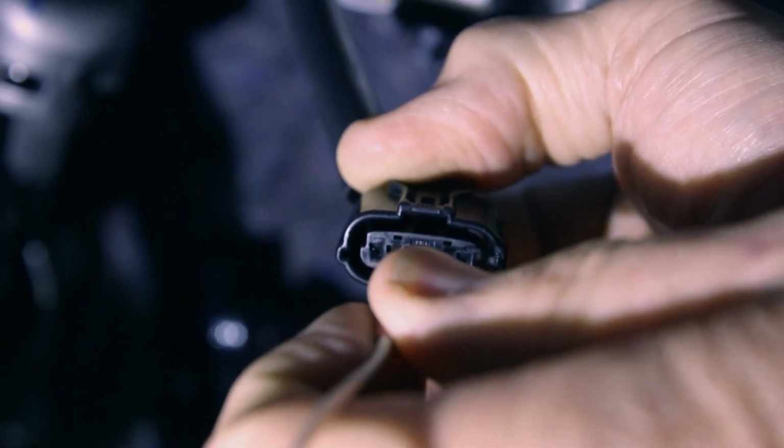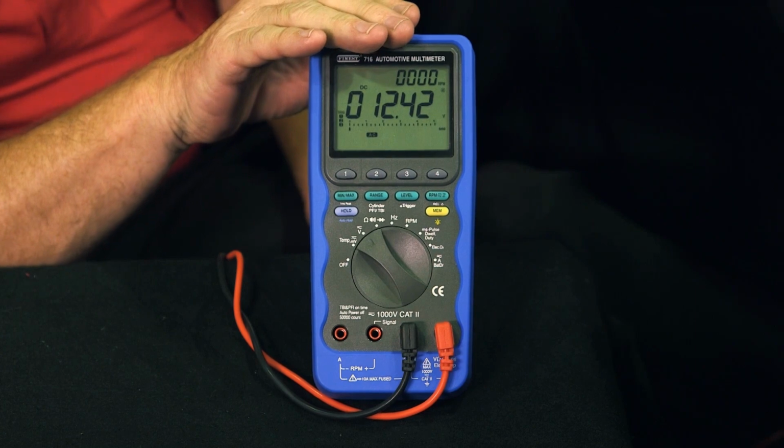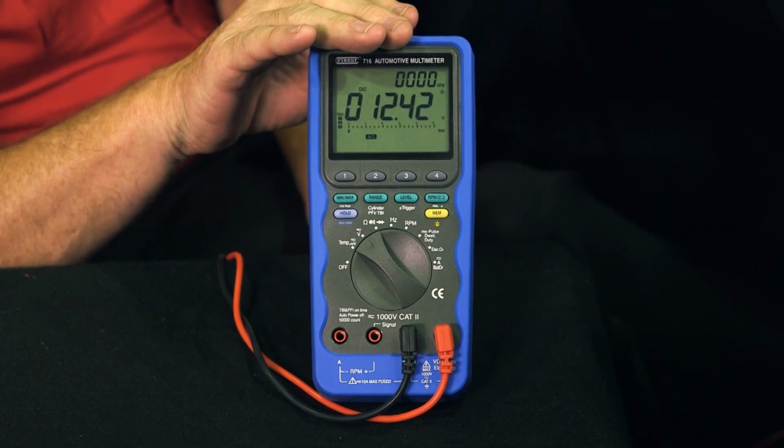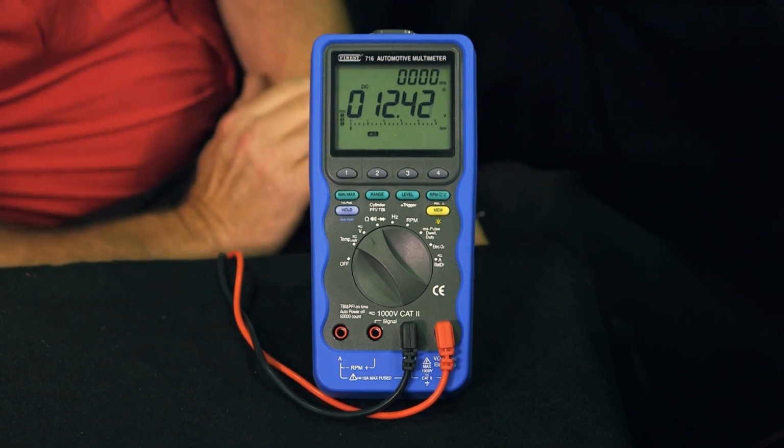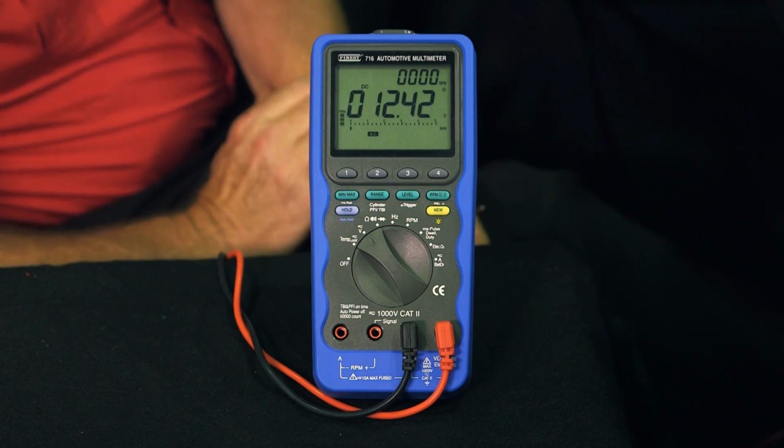So we'll now move the pin across to the signal circuit. Because this is a pull-down circuit, there's no need to move the other multimeter lead. We're looking for 12 volts because we're connected between B+ and a pull-down circuit. Let's have a look at the meter and see what our reading is. There we have 12 volts or battery voltage. That means that all the wires have the correct voltage. So the most likely cause for this fault is a faulty accelerator pedal position sensor.